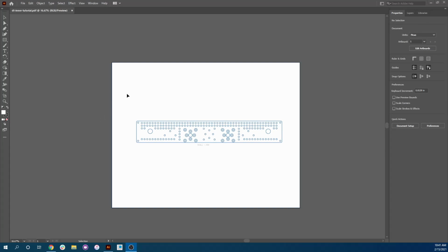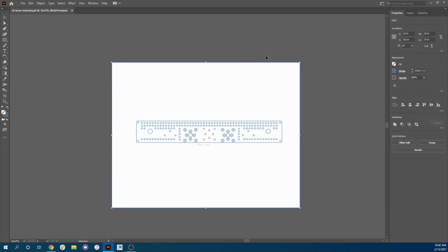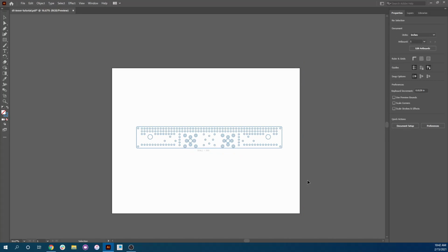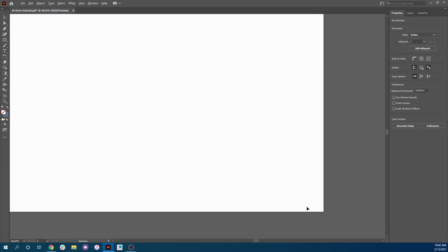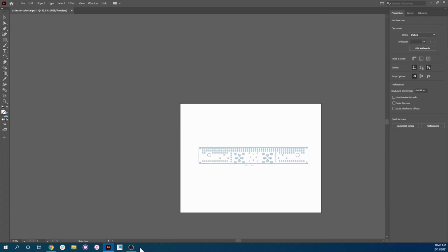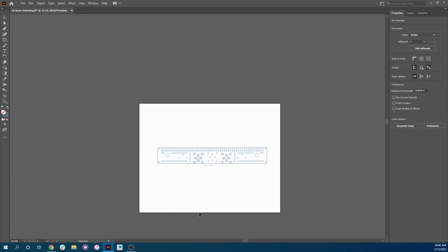So first off, with the weird things we have in Creo, and I believe they exist in most parametric CAD software when you export parts, there's a bounding box around the outside. You can't really see it, but if you drag your mouse over it, you can see that this box highlights. So what you want to do is delete that, so all of those lines go away, because if you leave the lines there, the laser cutter will actually cut them. So you don't want that to happen. Obviously we need to remove those.